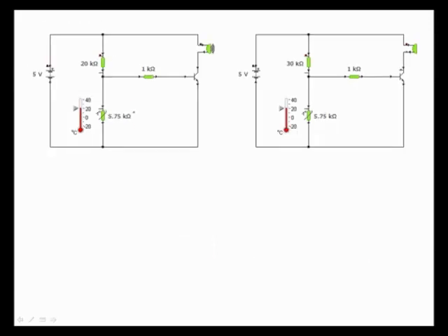So what I could do is, it seems the most obvious thing to do would be to change the thermistor, change the temperature sensor, but that's not very viable, because they only make a few different temperature sensors, and they work within a certain range, but they make hundreds and thousands of different types of resistors, and all I'm trying to do is change the voltage at this point here so that it goes to above 0.7.